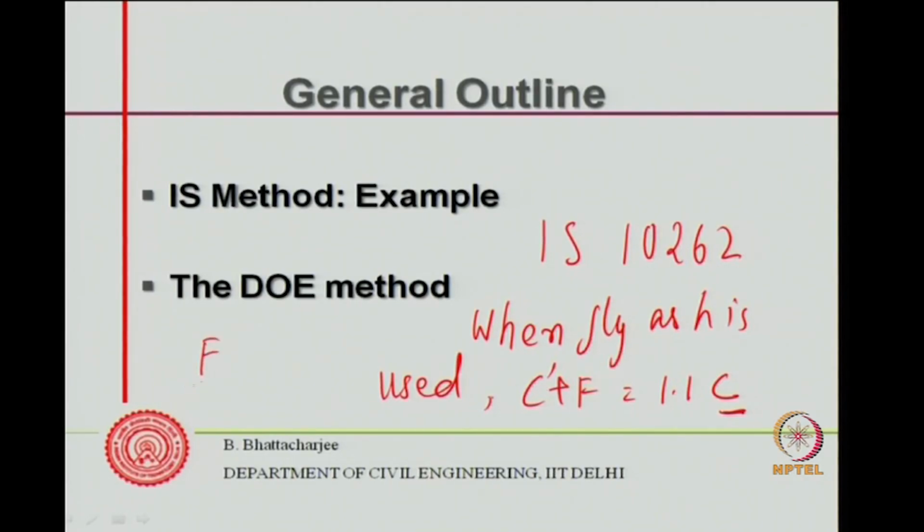So, if you know F divided by C dash plus F, we have decided, let us say, to use 20% fly ash in the system. Then from these two equations you can find out the fly ash and the cement content itself. One is that you increase the total by 10%, so 1.1 C. You have a control mix without fly ash, which will have a cement content of C kg per meter cube. Now, if C was, let us say, 320, then C dash plus F will be something like 352 or so, somewhere close to this. You can approximately take that guideline.